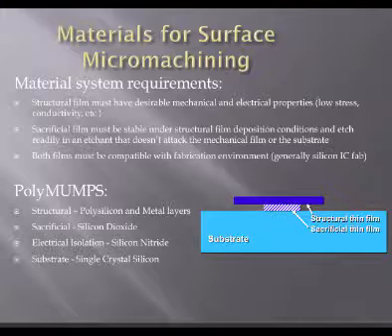If you hold something down that's stressed, right, you can keep it nice and flat. If I let go, it's warped. So if you don't have low stress mechanical materials, structural films, you release it and those cantilevers will bend. The mirrors you're trying to make will be warped. They'll look like potato chips.